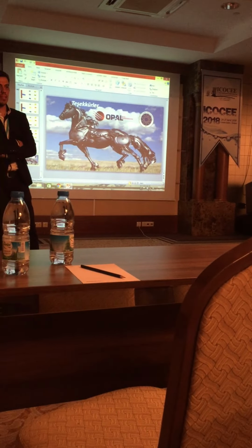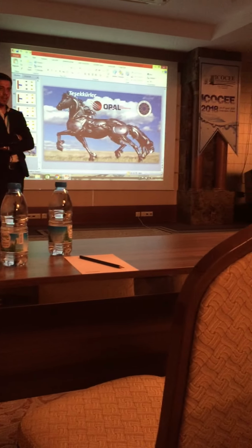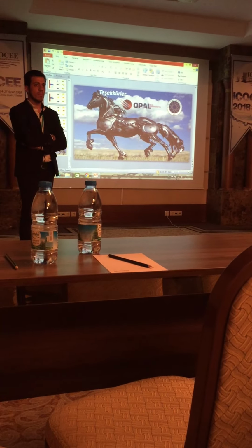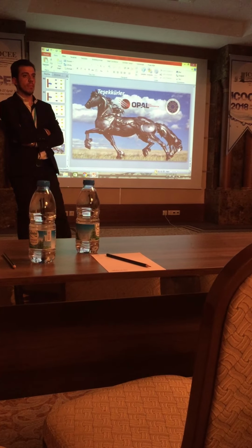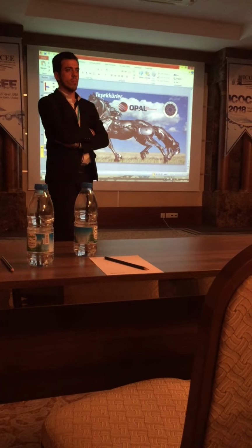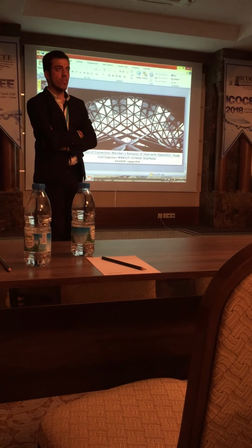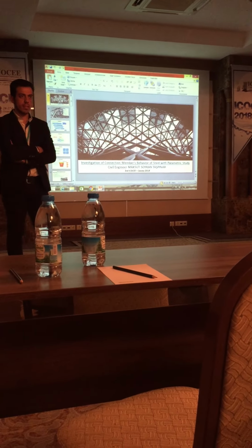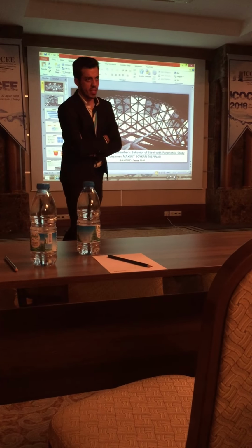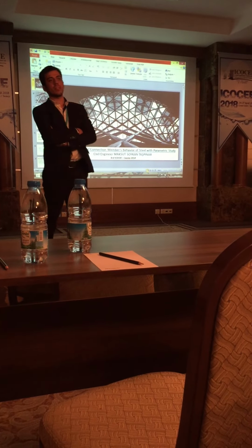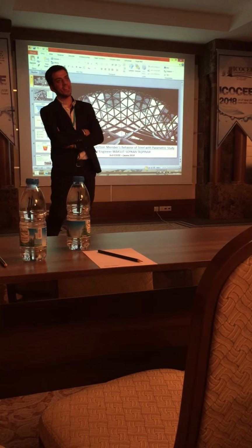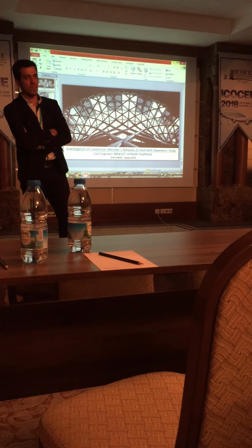May I have a question? Yes, of course. Thank you very much for your interesting presentation. Thank you. I wonder which type of elements you used in Abaqus? Which type of elements we used? Solid elements, homogeneous materials. And steel materials, S235 and S275 grade materials we used.